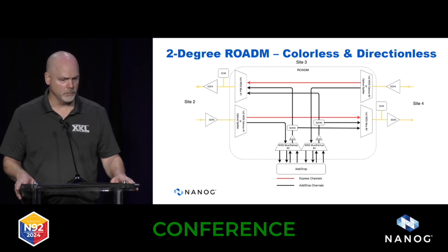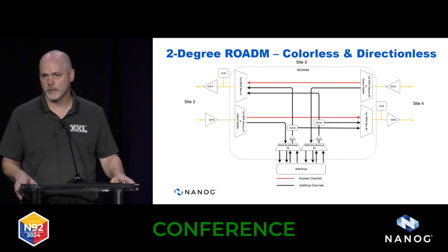Also notice here we have something called the optical channel monitor, the OCM. That's so that you can see the different channels coming out of the WSSs, so you're sure you're passing what you want to pass through. There's also an equalization function, which I'll talk about in a minute. But you want to be able to monitor all the channels in the DWDM network, and that's what the OCM is doing.